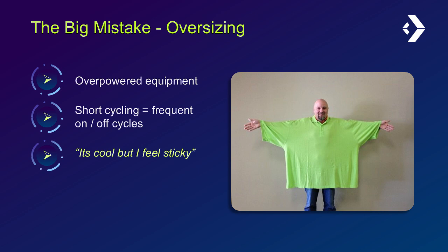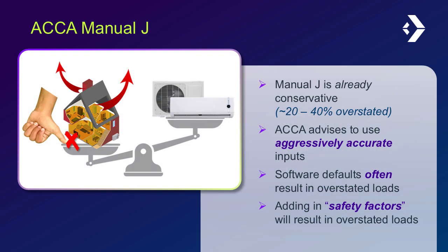When you follow a Manual J, you can prevent sizing mistakes. The calculated load number anchors us. Manual J gives a defensible, data-driven calculation. The big takeaway is, good comfort starts long before the equipment shows up on site. It starts with a proper load calculation. When we can understand the actual heating and cooling needs, everything downstream, equipment selection and duct design, better falls into place. Manual Js aren't paperwork. They're the roadmap to doing heat pump projects the right way.